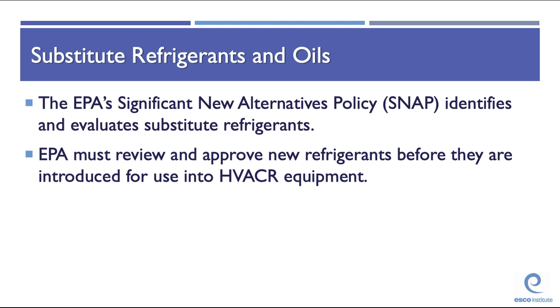The sale of CFC and HCFC refrigerants has been restricted, okay, since November 1994. The sale of ozone-depleting substances and substitute refrigerants, HFC and HFO refrigerants, is only to certified technicians as of January 1st, 2018.